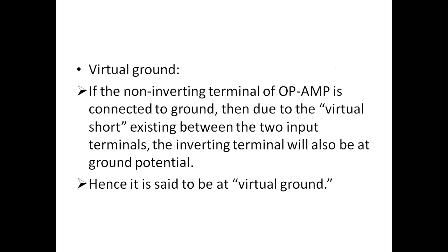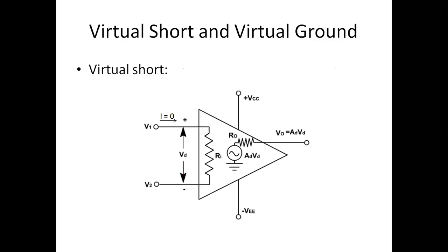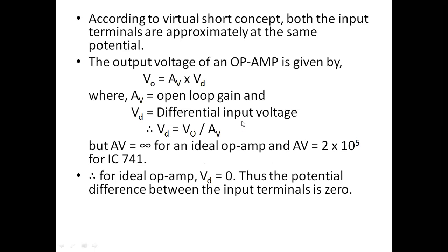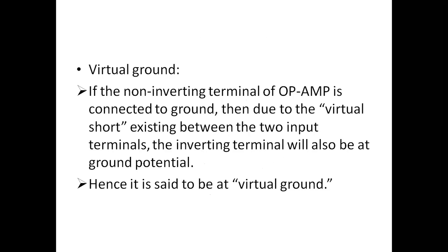Now we are supposed to study about the virtual ground. If the non-inverting terminal is connected to the ground, it means what? The positive terminal. Then, due to the virtual short existing between the two terminals, the inverting terminal will also act as a ground. What we are doing here, when we study the virtual ground concept, is that if the non-inverting terminal, that is nothing but the positive terminal, we connect with the ground, at that time we can say, due to the virtual short